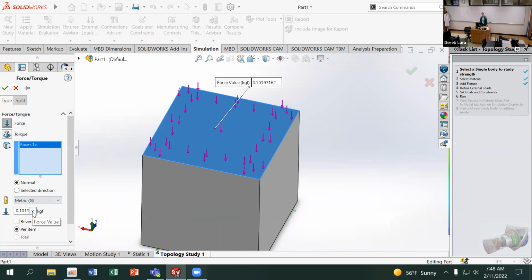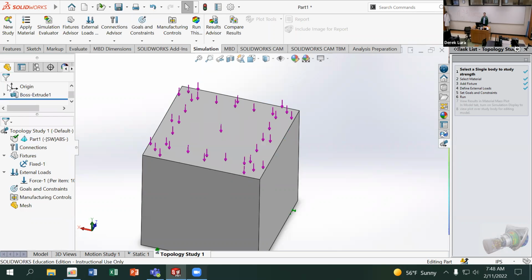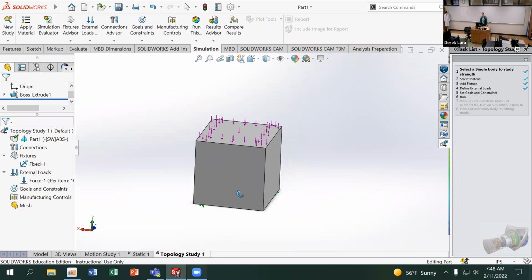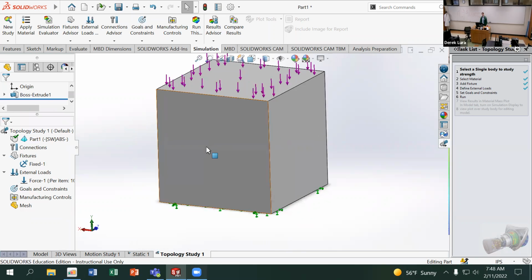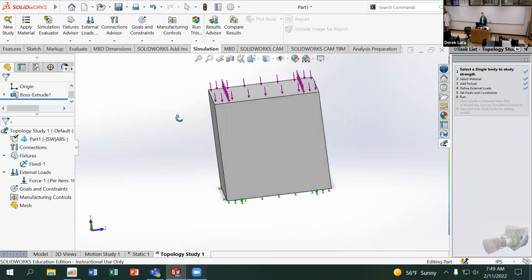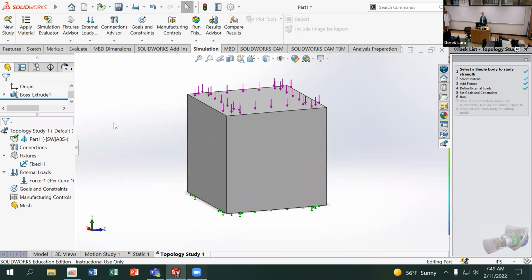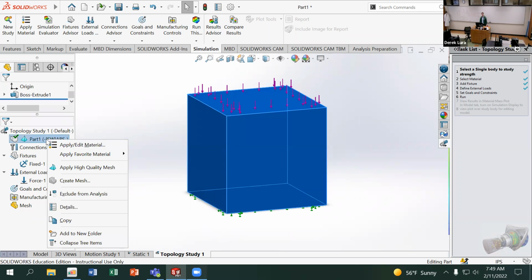And if your model has a reasonably low factor of safety to start with, then it's actually a little bit easier in some respects because it will not have to remove as much material to achieve a more appropriate factor of safety of say 2 or 3. But if you are doing this, chances are you do have a pretty significant amount of material to remove, and so these kind of considerations that we'll talk about here become important.